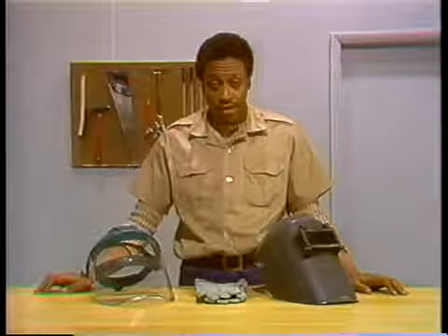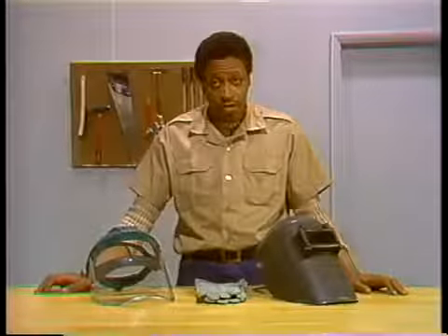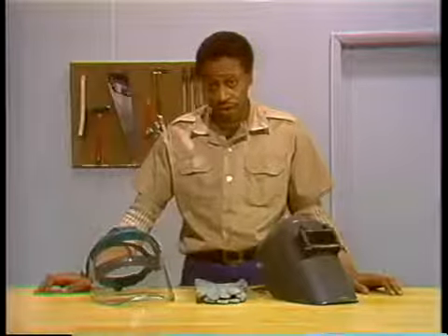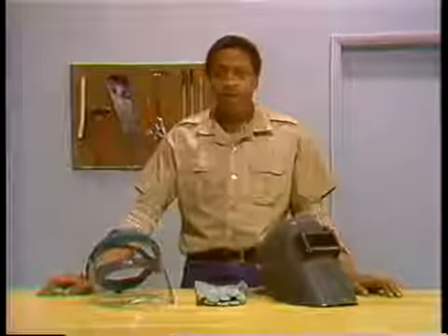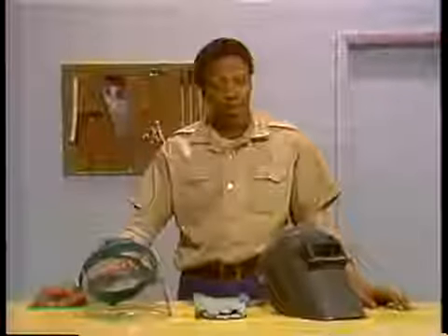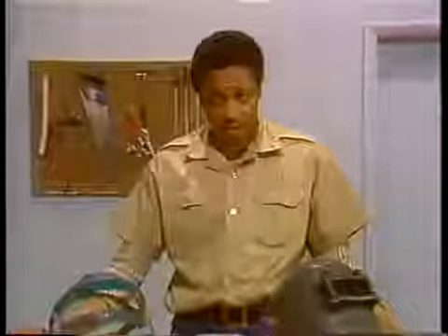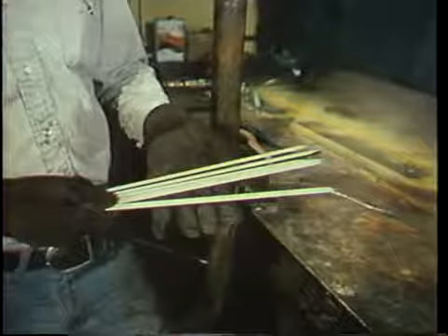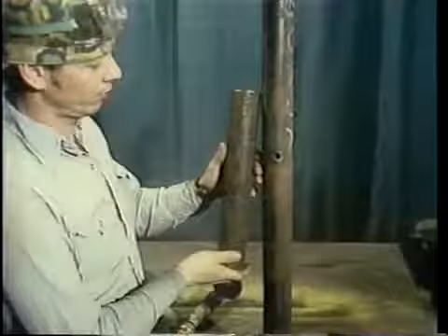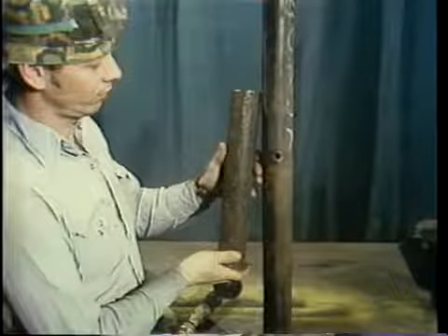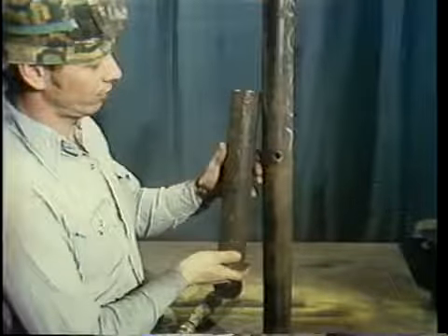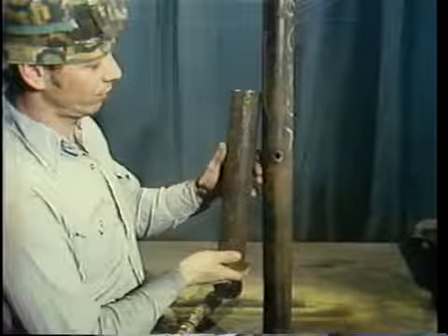As with other repairs, the first step is to familiarize yourself with the procedure. Read over the written instructions or talk to an experienced welder. Then, get your materials and equipment together. You'll need some welding rods and a length of tube from which to cut a replacement piece. The replacement tube must be of the same size and material as the original tube. Check your boiler manufacturer manual to find out the makeup and dimensions of the original tube.